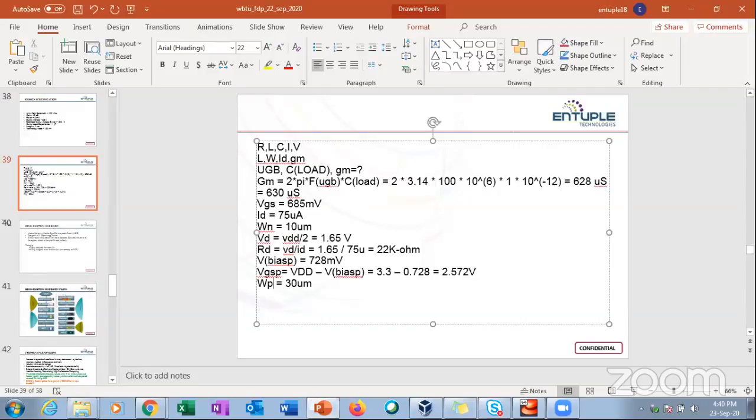Because in a P-type MOSFET, holes are the majority carriers, and there is a requirement of an additional force to create a hole. Because of that, the mobility is also less when compared to electrons. So the width is taken as either twice or thrice that of the NMOS transistor, and that is based on the mobility ratio of both the charge carriers.